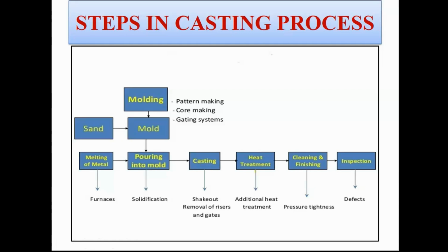So sometimes some heat treatment is followed, and that heat treatment will particularly be annealing or normalizing, so that it will restore the ductility of your cast product. And restoration of ductility is also a very important aspect, because you all know that casting can be full of defects.